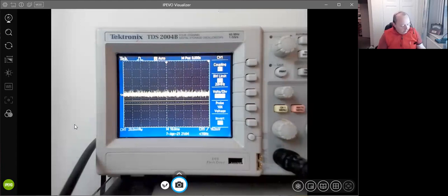This was about 10 minutes before we started. I was just running through things, about 7:15, and I thought, oh my God. So I just put 100 nanofarad across the output, and everything quietened down. But it comes to the point, John, that a 0.1 penny component in the right place can make a world of difference to your design.